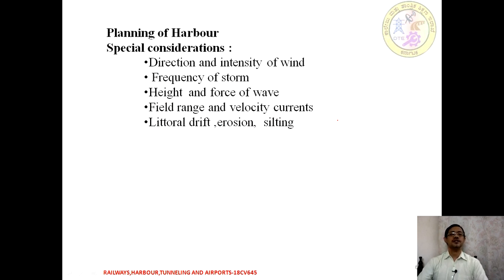Some more special considerations have to be taken into account while planning a harbor. In that criteria, the direction and intensity of the wind play a very critical role in aligning our breakwater or any other coastal structure. Next is the frequency and occurrence of storms. Next is the height and force of waves, tidal range and velocity of currents. Next is the littoral drift, erosion and silting. So these are some special considerations to be made while selecting a site for a harbor.